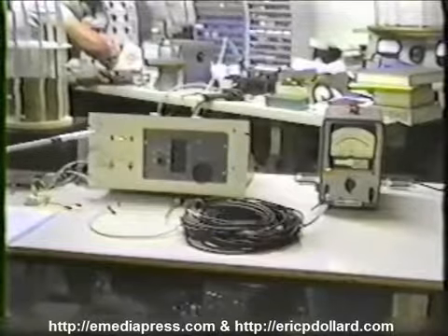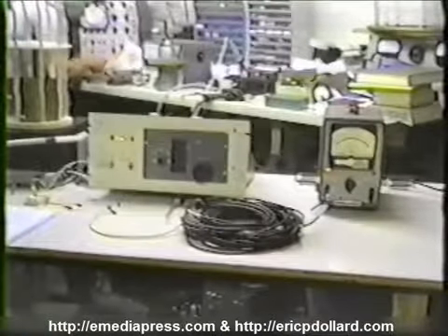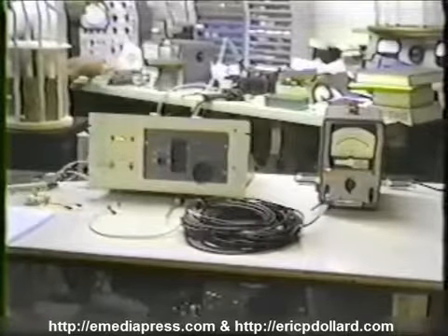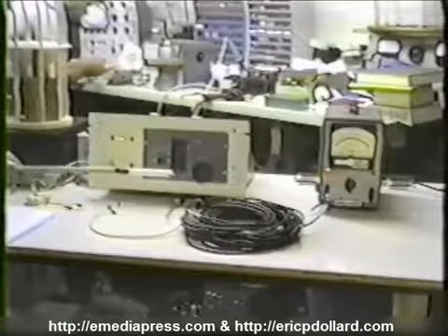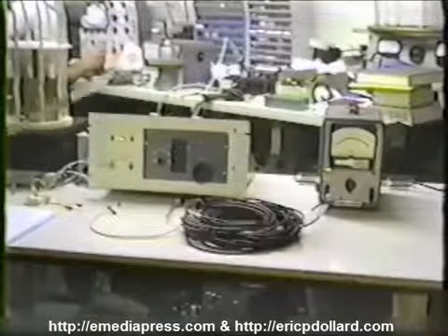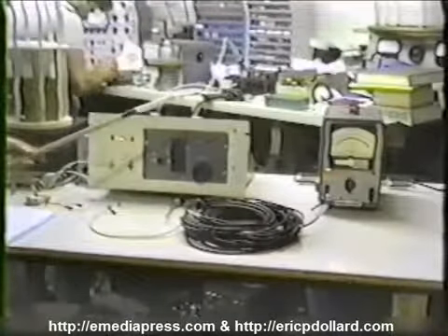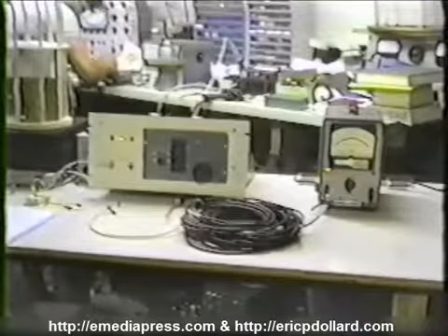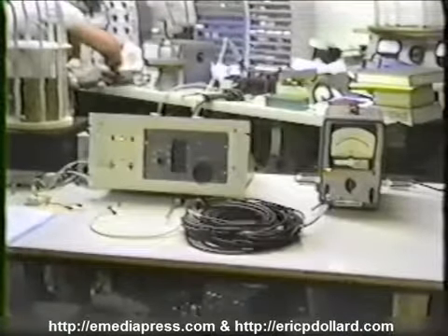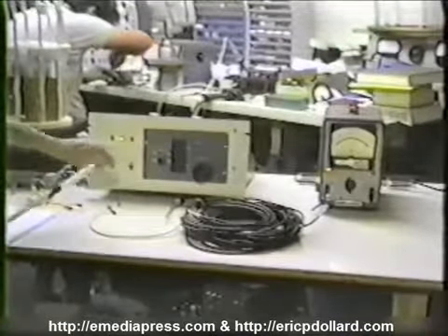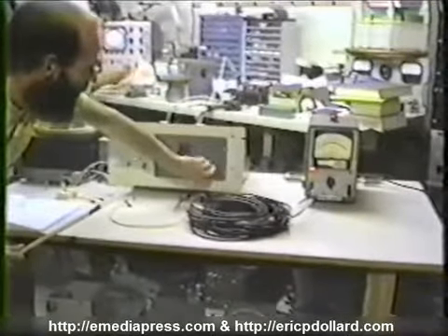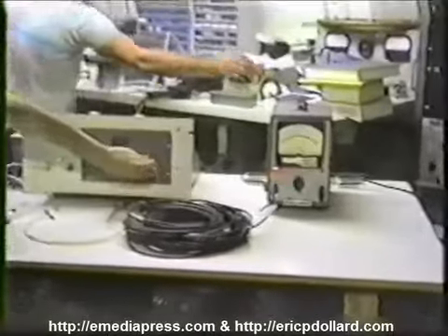The oscillator has gone through another 180 degrees of shift and is producing a right side up impulse to match the reflected inverted, or now right side up impulse. And this process keeps on going on and on until the voltage rises to a level where the losses of the system prevent any further increase. So what we're going to do is sweep the frequency here and find the resonance point of this cable to determine the propagating velocity.